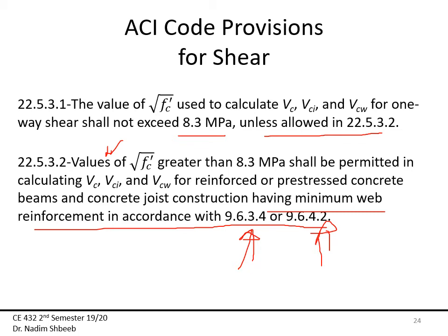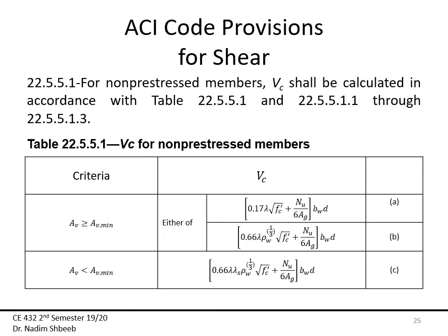We usually pick a critical section near the support somewhere, and that's in part also because at the supports, at the columns, it's usually heavily reinforced as well. So there's a lot of reinforcement there. It would be kind of counterintuitive to design according to the support reaction at that location. Instead, we'd like to move a little away from that column, which is usually heavily reinforced at that section.